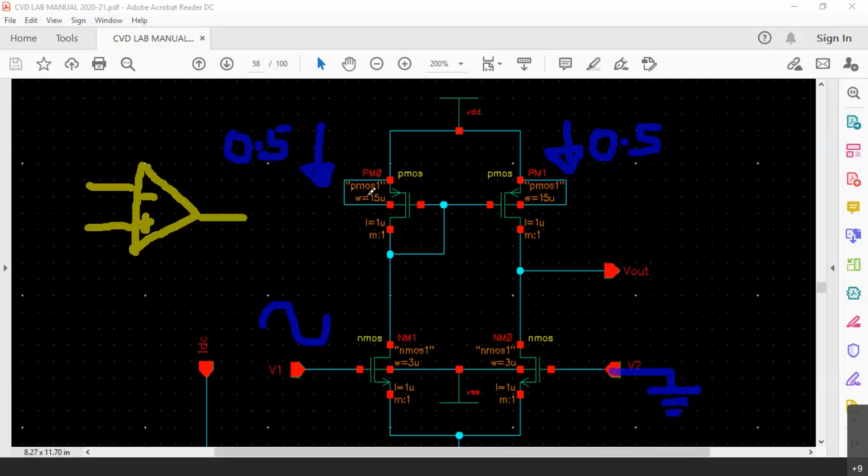As I keep repeatedly telling you, in case of BJT, whatever we call saturation, in case of MOSFET we call it the linear region. In case of BJT, whatever we call the active region, we call the saturation region in MOSFET. This should be very clear to you always. It is two different sets of scientists who invented and worked on these devices.